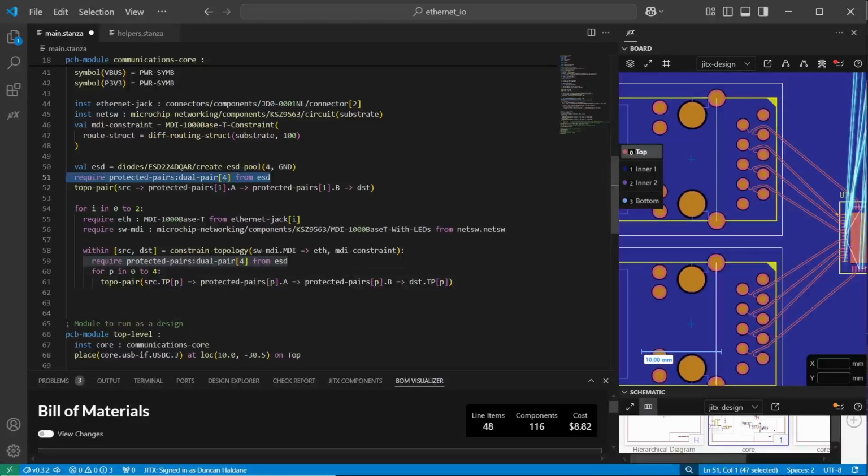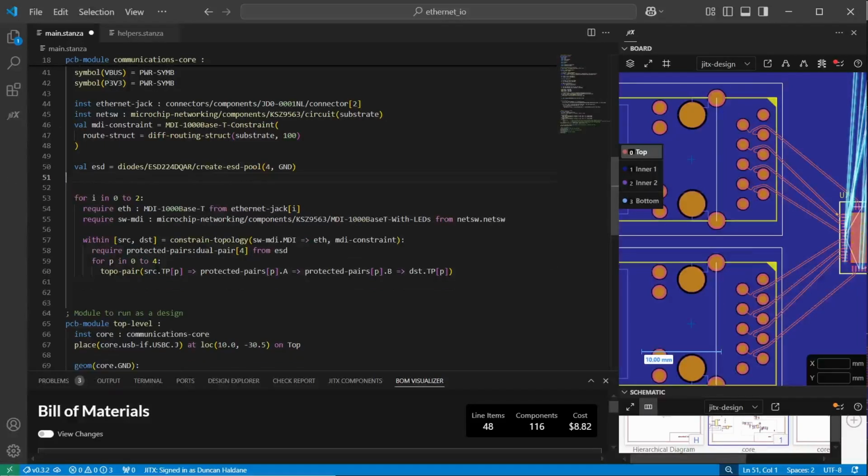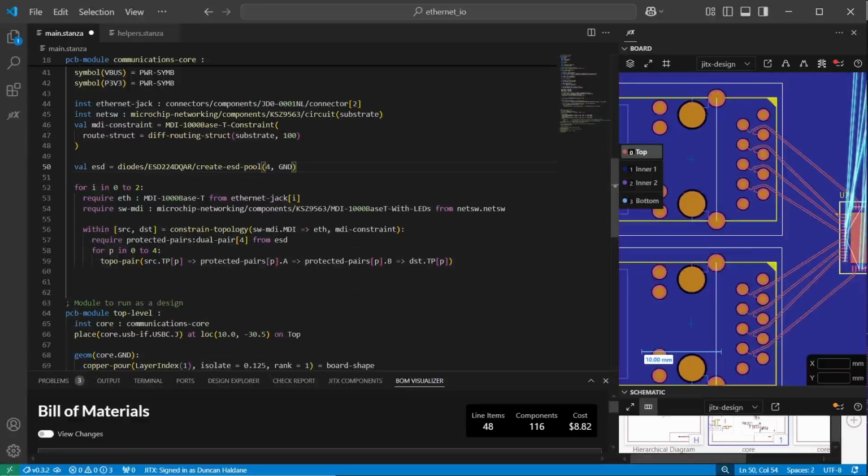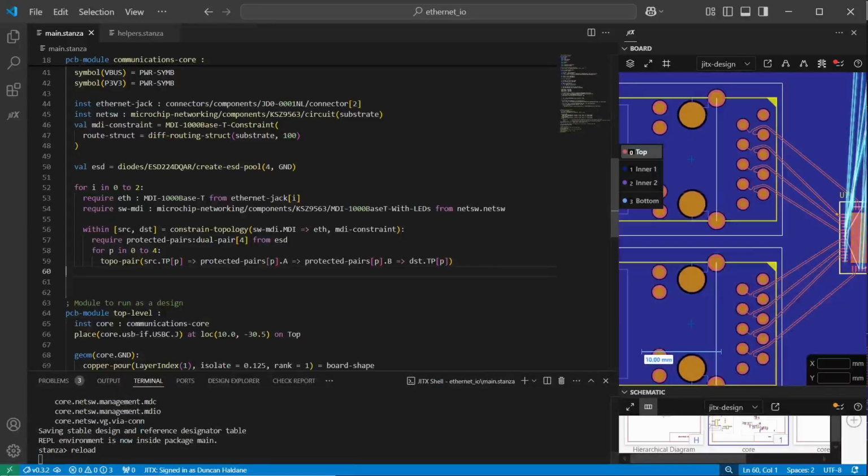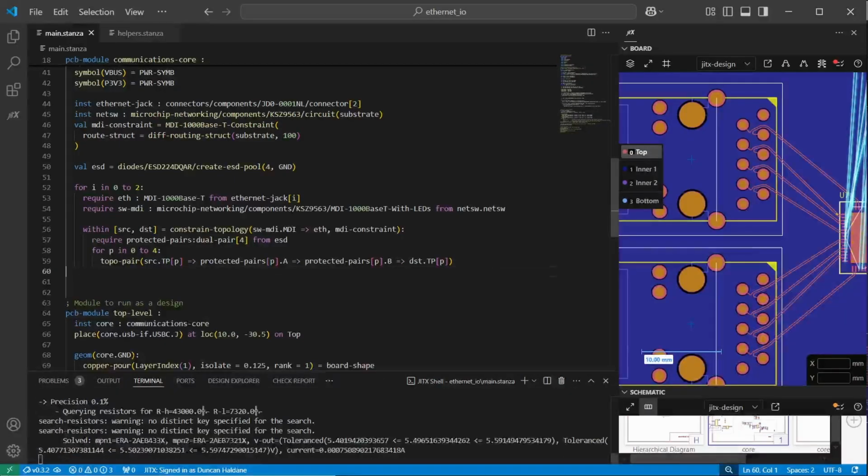So we don't need that line, and we don't need that line. There we go. And then that makes the connection from the source down through the destination. Okay. That looks good. And that's about as complicated as signal integrity code gets, where you have a non-trivial topology constraint through multiple components, closed end-to-end with skew and loss constraints.